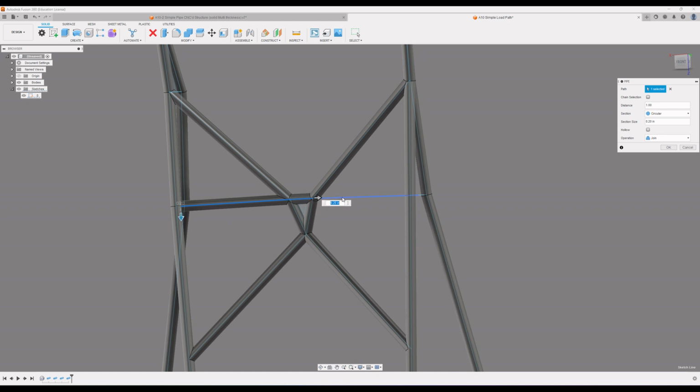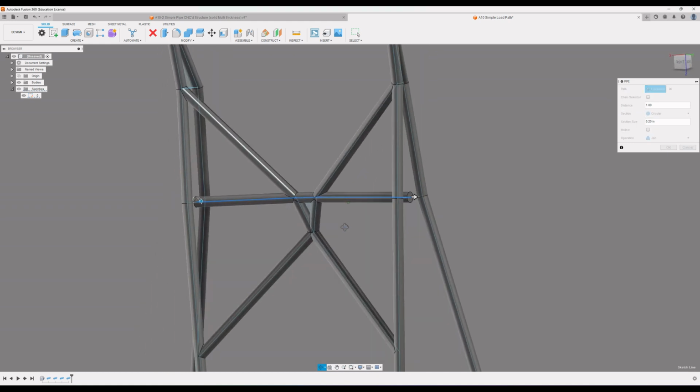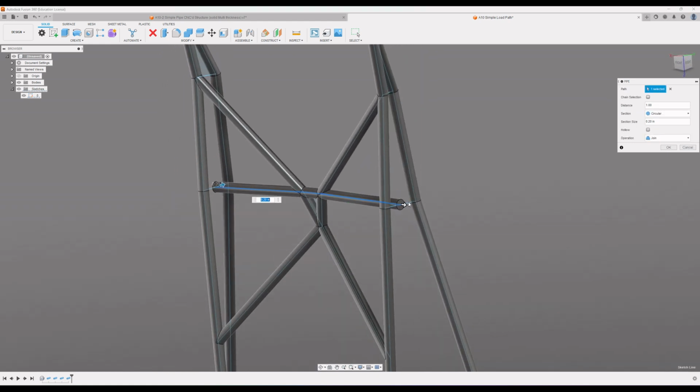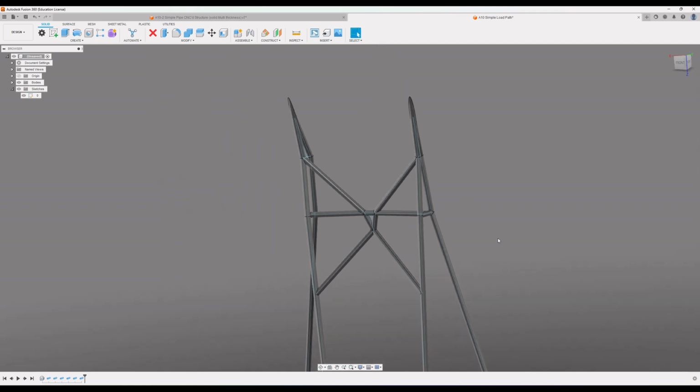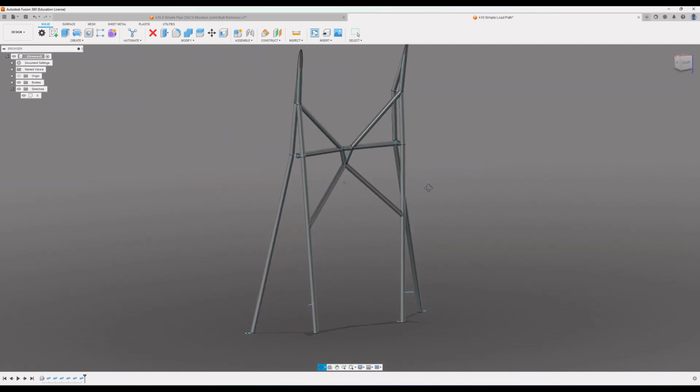We also don't need to worry about planes or anything like that. This will just produce a pipe along those lines. And you can see here we have that little angle right there. No need to worry about connecting. You can just use the pipe tool, select that central piece right there, and it will go ahead and build out the connections between all of those connecting pipes. It doesn't really matter what order you do it in. If you do those first, if you do them second, it'll still produce the same geometry.